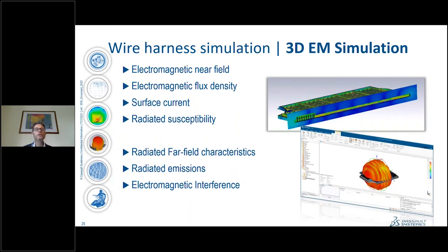And here we have a unique solution because in our method, at each time step, at each delta t, we have an exchange of information between the 3D electromagnetic code, a circuit simulator like SPICE that we have in CST Studio, and also the cable tool that basically calculates the crosstalk between cables on a specific cross section using a 2D method.